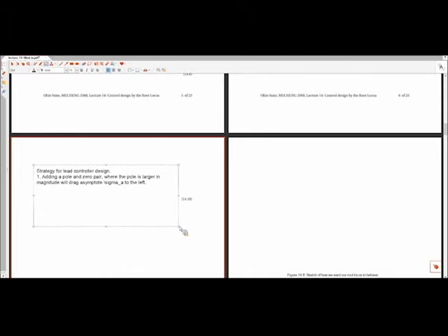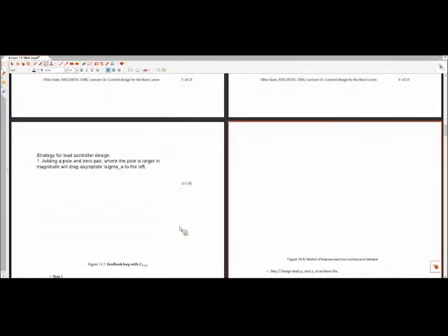Okay, so what that means, when we say adding a pole and zero pair, is we are adding to the system. Instead of saying that we just have a simple proportional controller, which is what we had before, we're saying that we have a gain on our system that we can modify. We have then a pole zero pair that we're going to add to our system.